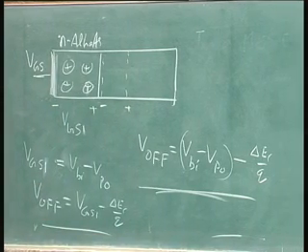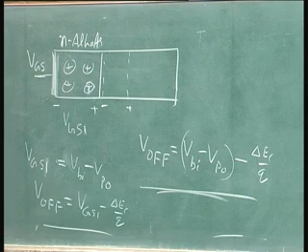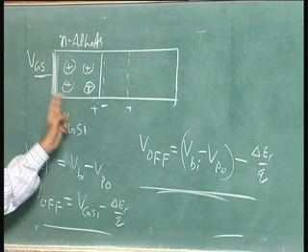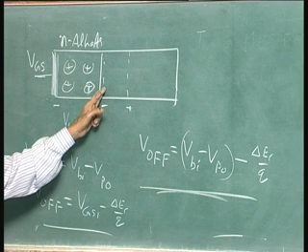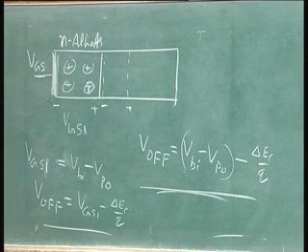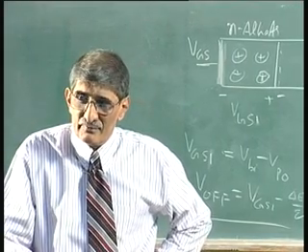So, that is actually the voltage that you must apply to the gate to turn off the HEMT, to ensure that electrons are just barely minimum. There will be still some electrons, but minimum, not sufficient for conduction. It is just like the MOSFET. In a MOSFET, you say threshold voltage is the voltage at which the MOSFET is turned off.